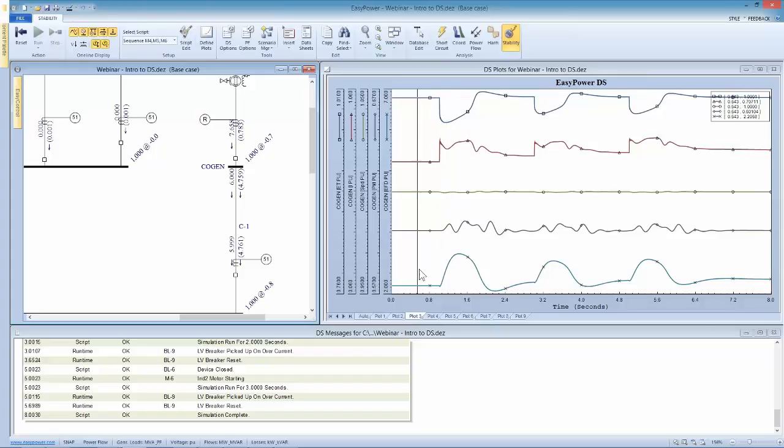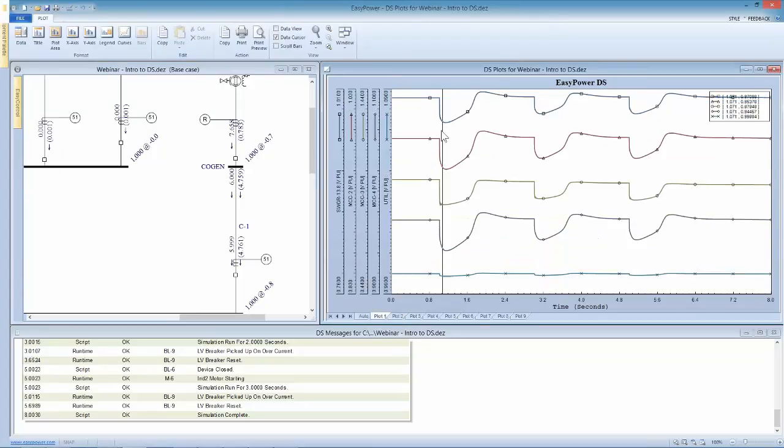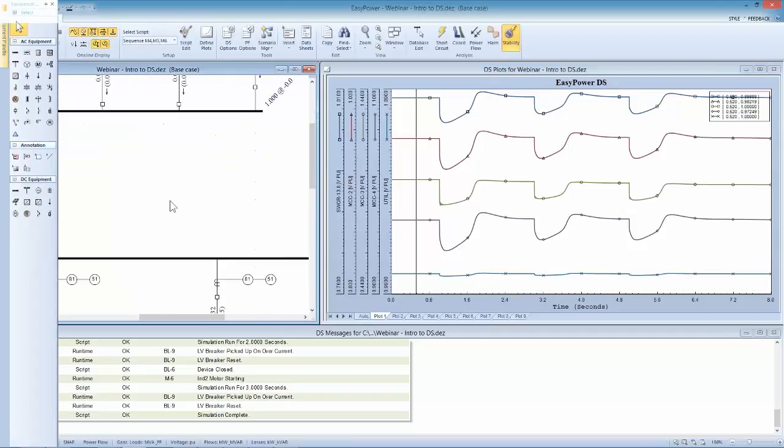But one of the transactions that we didn't expect is the fact that we're actually getting voltage above the normal control level, and it affects even the other motors on subsequent or sister buses. So this first one is a utility bus. The second one's MCC2, which is another 480 volt bus, and then even the 4000 volt bus. Let's look back down here.